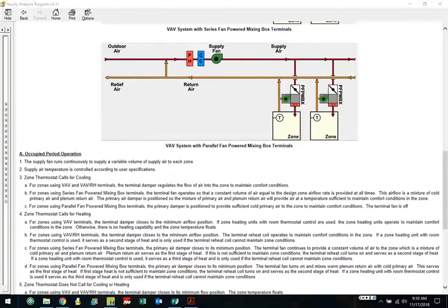And our heating coil here is going to have hot water. So I'm going to have a hot water coil in the unit. I'm going to have a hot water coil on each one of the fan powered boxes. I'm going to have a hot water coil on the internal zone. And space 107, the mechanical room, instead of leaving that with an electric heat, we're going to put a hot water heater in that also.